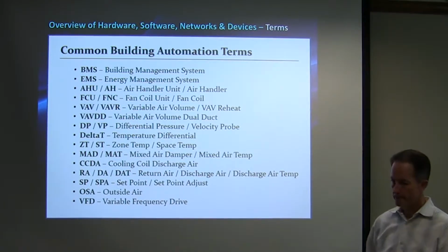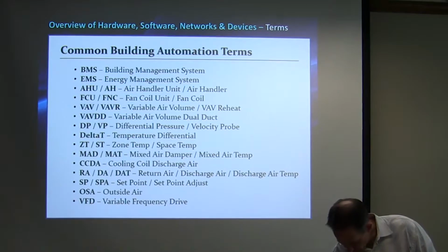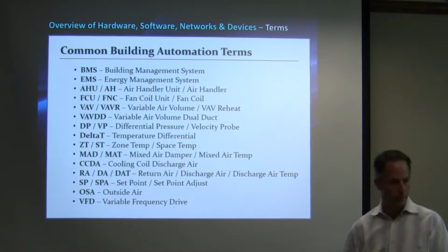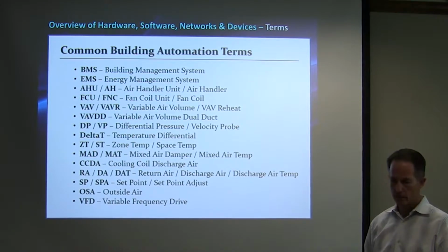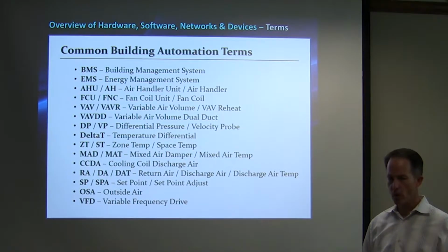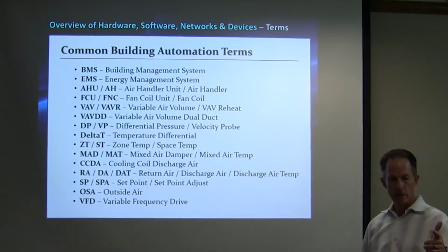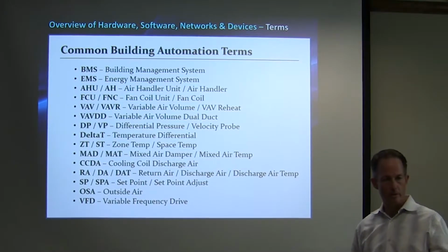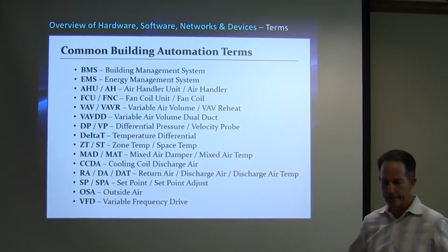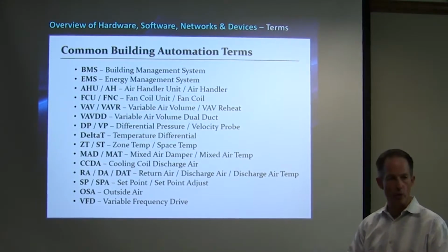Your PID, there you go, there's another good one. PID loop. Anybody know what that means? Got some idea. Proportional integrated derivative. Yeah, so proportional, integral, and derivative, and those have to do with the way that we apply changes based on an error to some sort of a value that we're controlling.